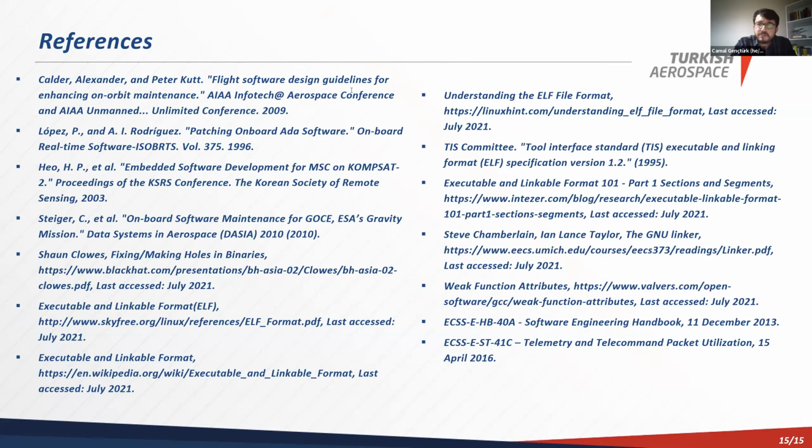Yes. Actually, our recovery mechanism is the approach that we are using, the bootloader approach, and we have the opportunity to go back to the original image. In some missions, especially if you see an error with your patched image, you need to go back to your original image. So we can say that this is our recovery mechanism for this case.